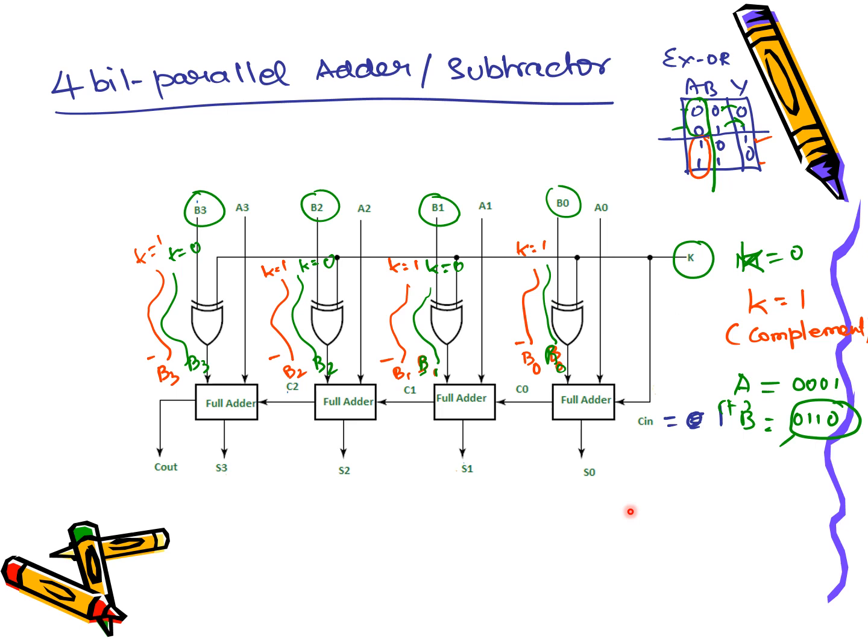Though we have these many circuits individually to perform addition and subtraction, and also a common circuit, we still prefer a carry lookahead adder. Why? They call it a fast adder. Look at that: each stage will give a valid output only when the carry is propagated from the preceding stage to this stage. Likewise for all stages, the next stage of addition has to depend on the preceding stage's carry.